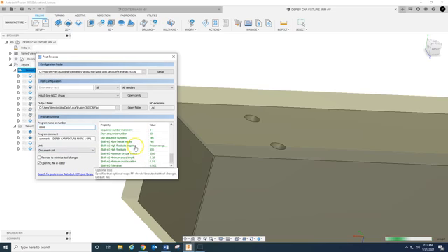And over here, you've got some different selections. It's asking me a handful of different options. Do I want to use optional stop? Do I want to preload the tool? The one that I primarily change the most is this. Put that on no, unless I'm on a machine that has a side mount tool changer.